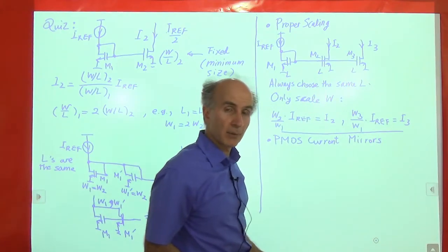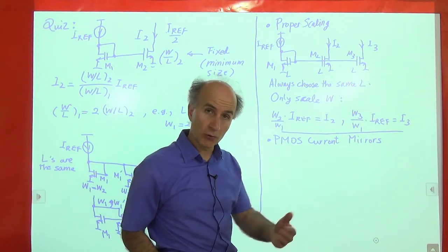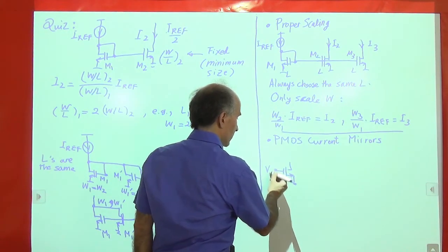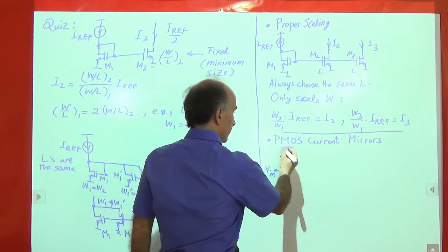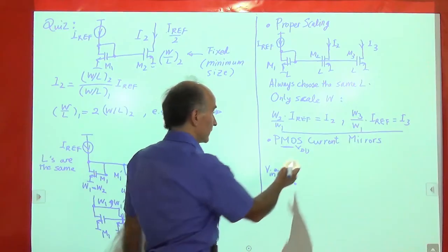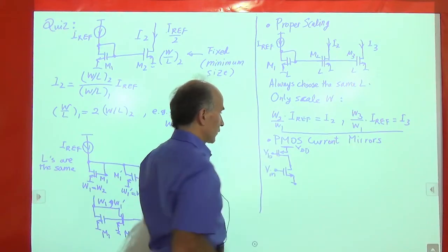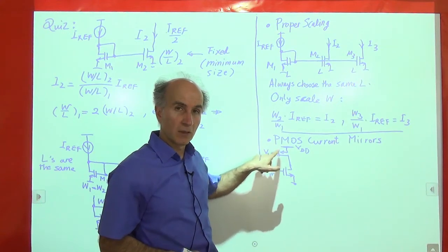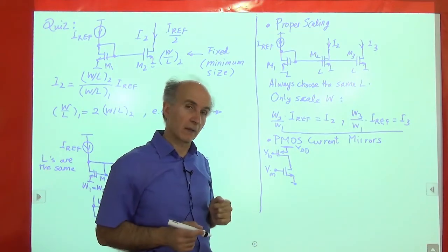So this happens too. For example, if you build a common source amplifier with an NMOS input transistor, so here's a common source amplifier with an NMOS input transistor, Vin, and now we want to have a current source as the load. That current source goes from VDD to this node, so it has to be a P-type current source. So that is a PMOS device with a bias. So our objective is to see how we can provide biasing for this gate voltage of this PMOS device so that its current is well defined and constant and all the good stuff that we talked about last time.